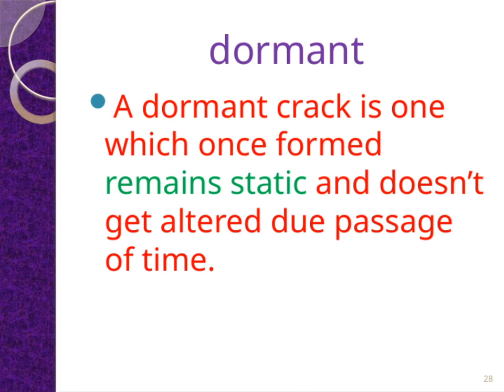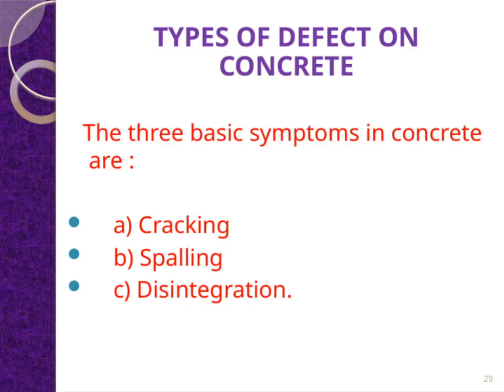Recognizing dormant cracks is important because they might not require immediate intervention, but we still need to monitor them over time as part of our overall assessment. So, in the bigger picture, knowing whether a crack is dormant or active is crucial for making informed decisions about maintenance and safety. Now, let's look at the 3 basic symptoms in concrete that indicate potential issues.